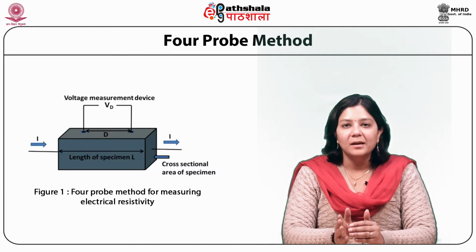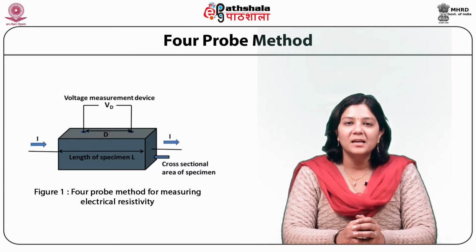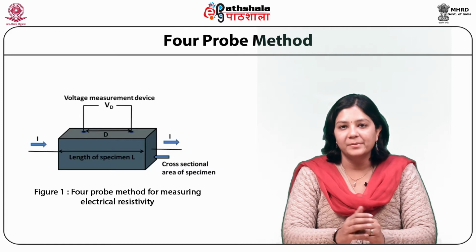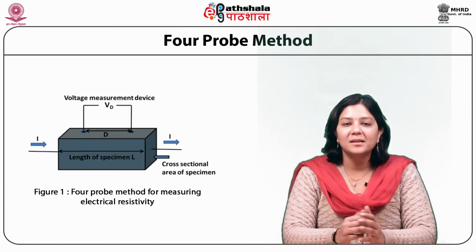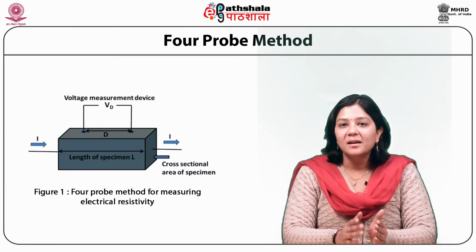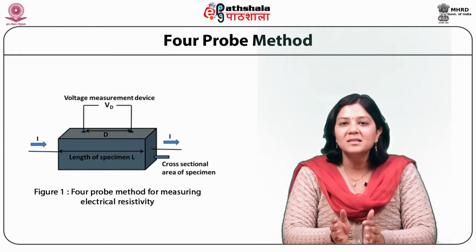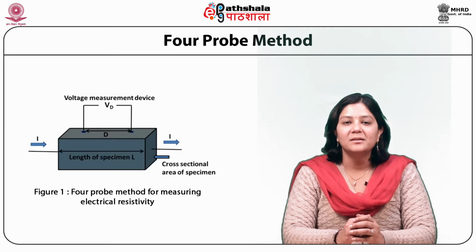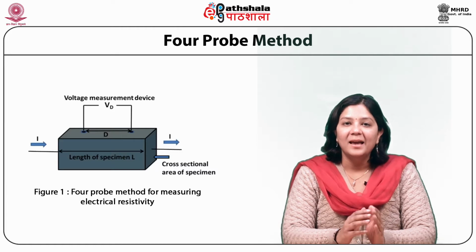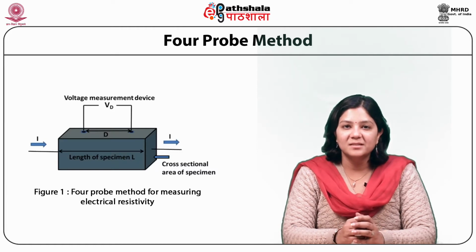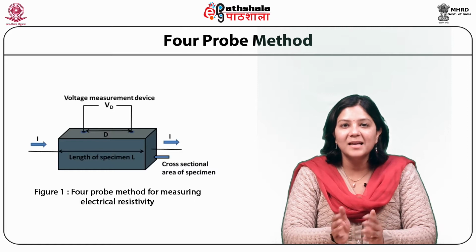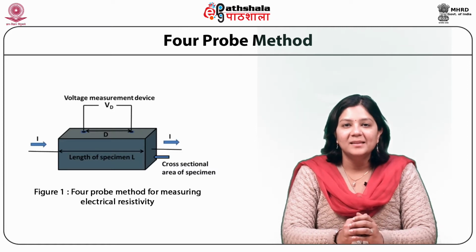Probe method equally applies to single crystal or bulk samples and can determine their resistances. Current flows through outer contacts near the sample edges and potential difference is gauged across inner contacts. Hence, the effect of interfacial resistance between electrodes and sample is eliminated. Thus, it is a precise technique for low resistance measurements.